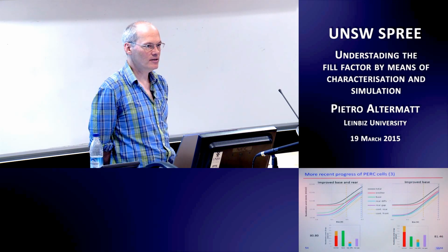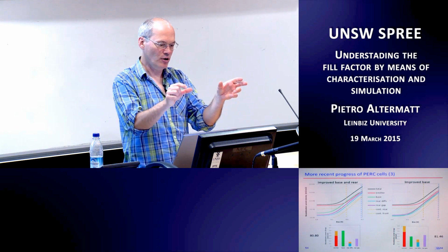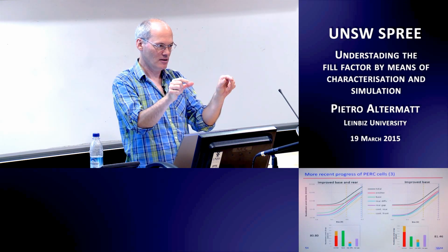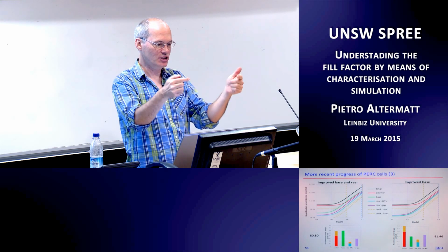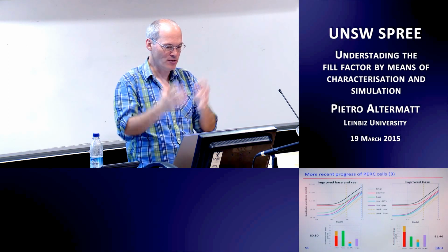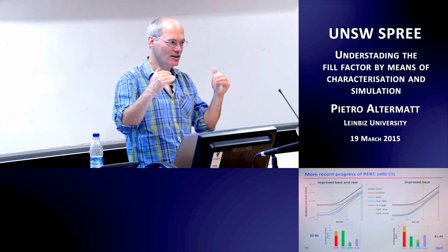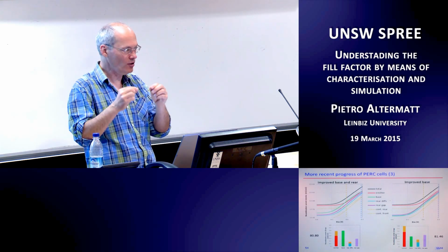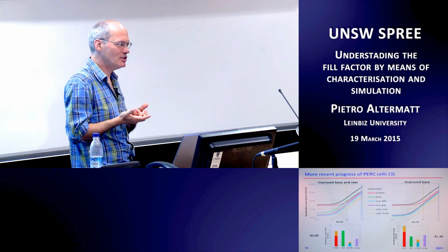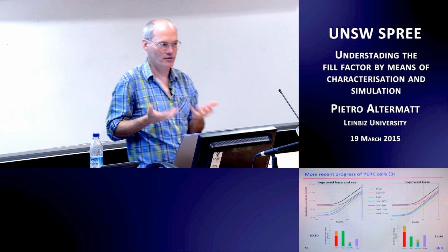But I mean, let's assume an emitter, and an emitter has quite a high sheet resistivity. You get a different injection level between the fingers and towards the fingers. And for a given J naught, you actually increase the recombination losses, because the losses in the emitter are not only a function of J naught. For a given constant J naught, they're a function of the local voltage along the emitter, of how you operate that junction. And this is actually what's often causing confusion about J naught, about saturation current.